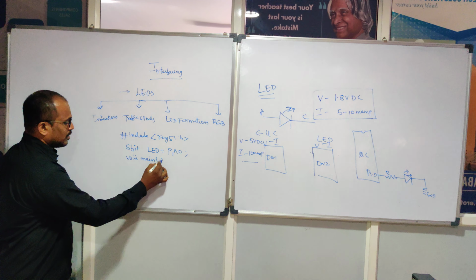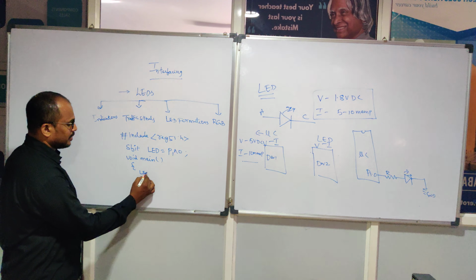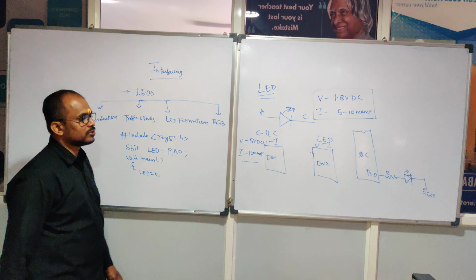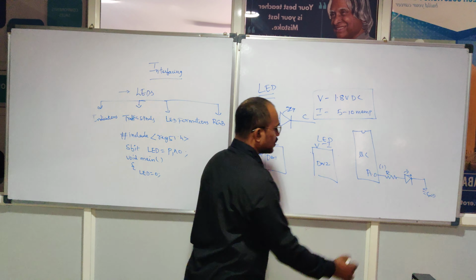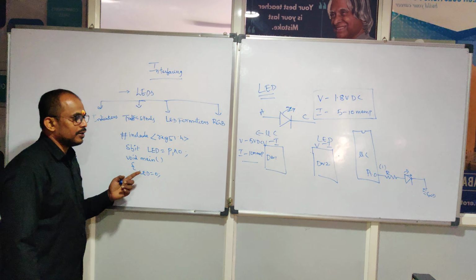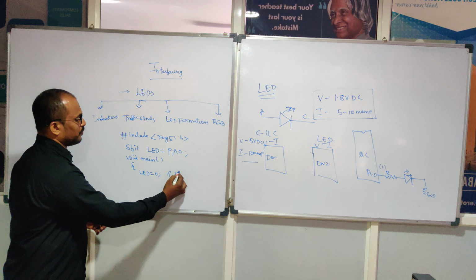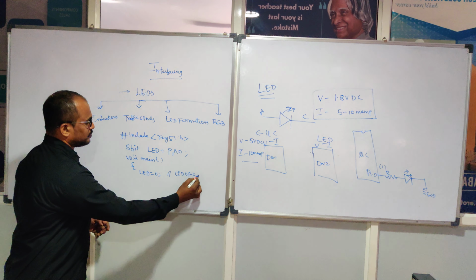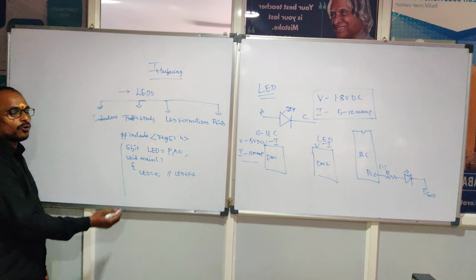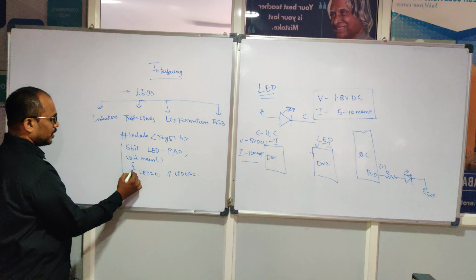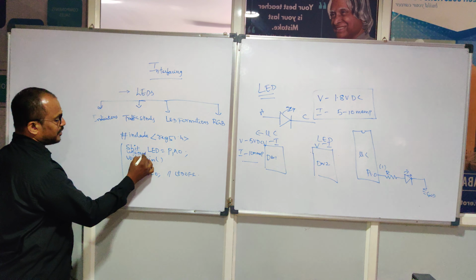main. And I'm trying to keep the LED assigned with logic 0, because by default all IO logics are ones from the microcontroller, and whenever you make logic 0 here, the initial status of the LED is off. And if you are trying to make an LED operation, you should take one variable compulsorily. That variable you need to declare with the int data type,